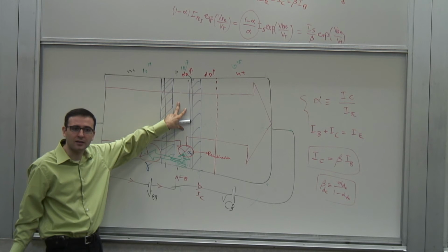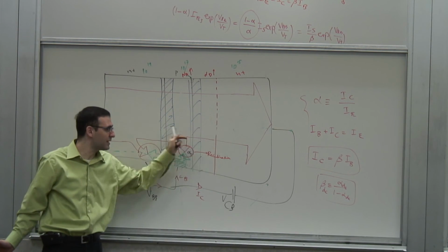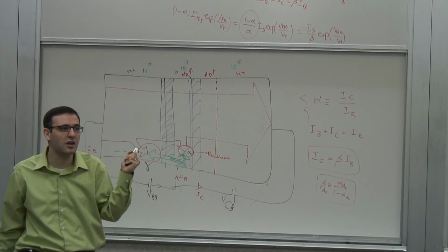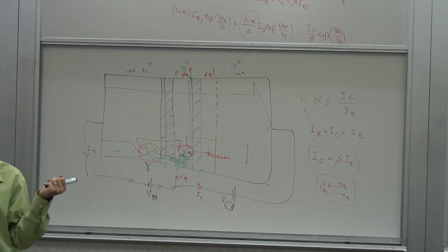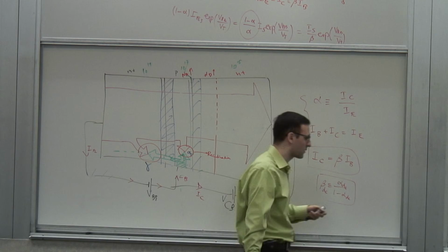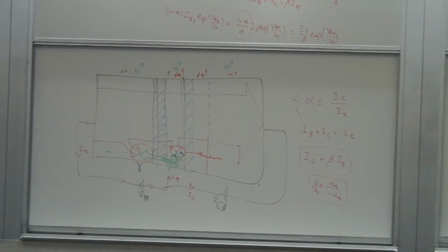They have to recombine. So it will take time for it to recombine, and during that time, there will be net current flowing through here. So the transistor doesn't turn off that easily because of this charge storage. And we'll talk about the dynamics in a second. But that's the essence, that's the physics behind it.